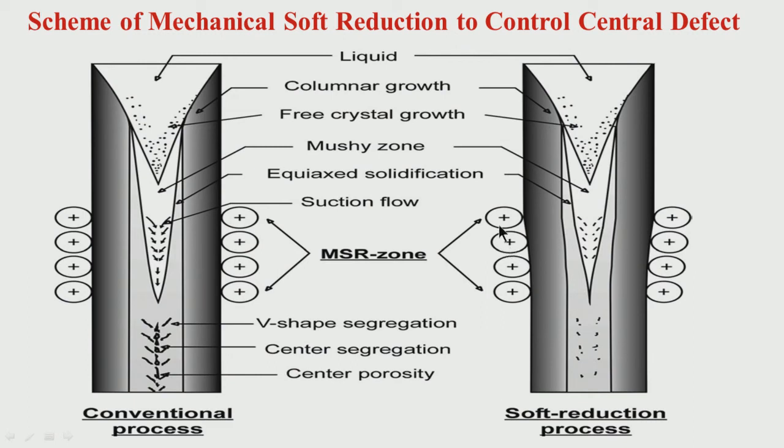That is why the pressure, the strain formation, is gradual. You are not putting a sudden pressure at any point of solidification. You are slowly putting the pressure. That is why it is called soft reduction, and that too, the reduction has a gradient. It is not one step of reduction; slowly it is increasing. As such, the total reduction is not much, but there is a gradient, that means slowly it is increasing. So this is an important concept.